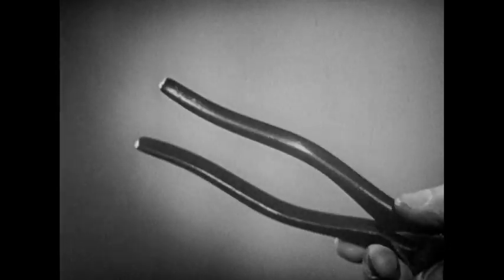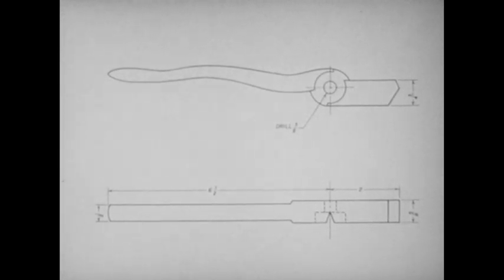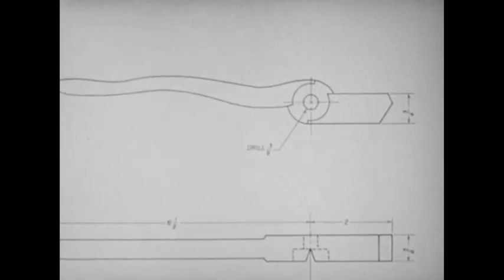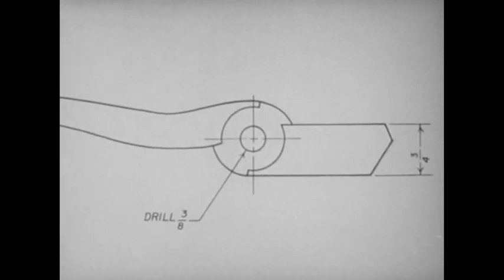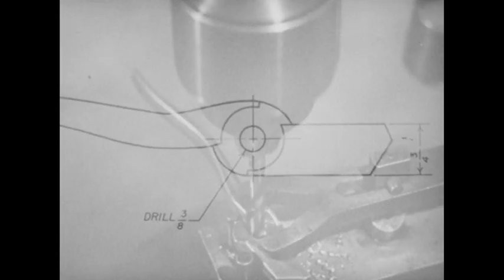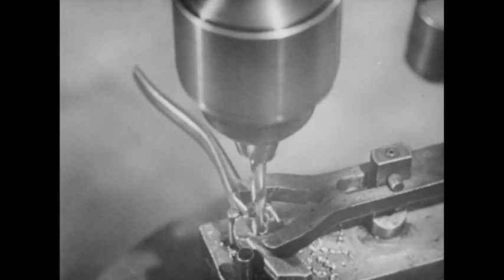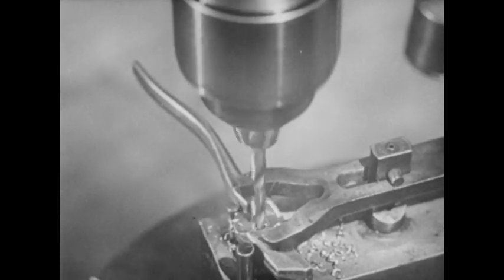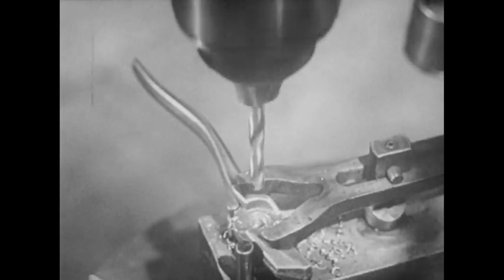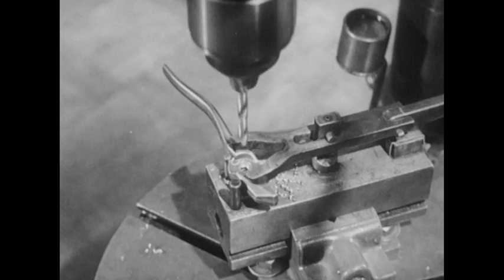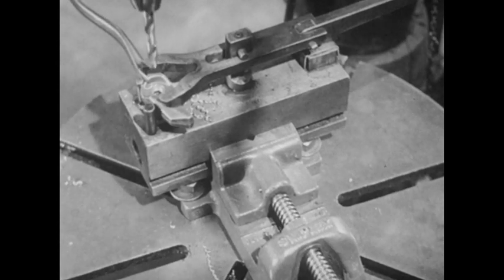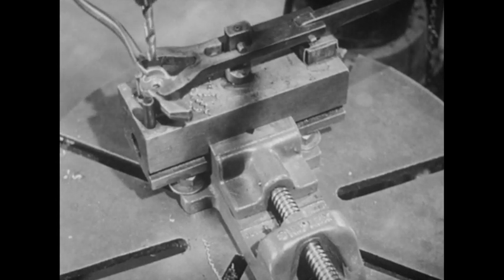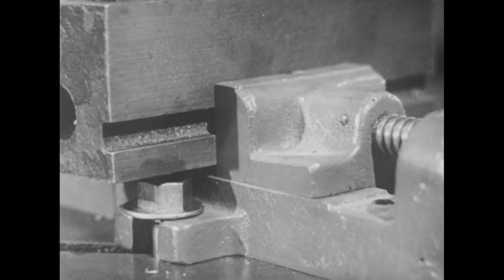In selecting dimensions, you must also consider the manufacturing process that will be used. Here, for example, the drawing shows the diameter of the hole rather than the radius, because standard drills are graded according to diameter. To understand further how function and manufacturing process influence your choice of dimensions, consider this drill press vise and imagine you have to dimension the movable jaw.